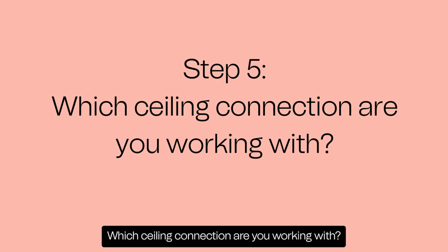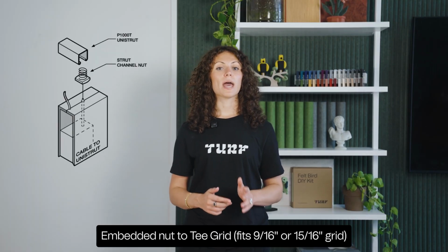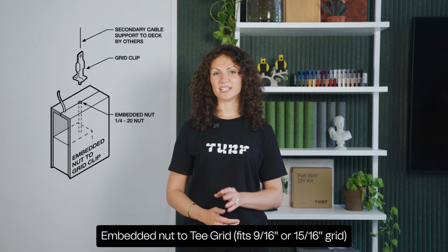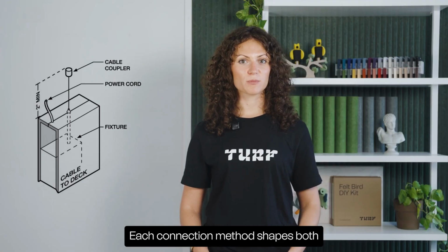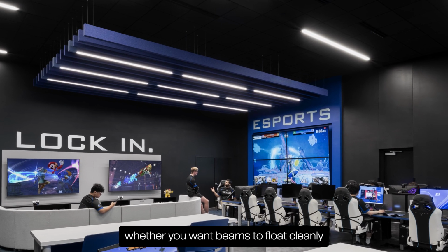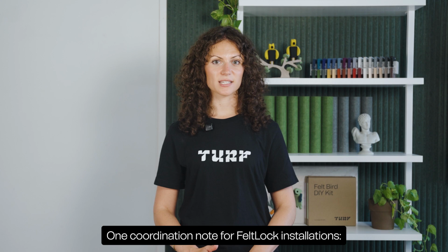Step 5. Which ceiling connection are you working with? Determine how Beam will connect to the ceiling. You've got 3 streamline options. Cable to unistrut, embedded nut to T-grid, fits 9/16 inch or 15/16 inch grid, or cable to deck for direct attachment. Each connection method shapes both the installation style and the final visual, whether you want beams to float cleanly or anchor with presence.